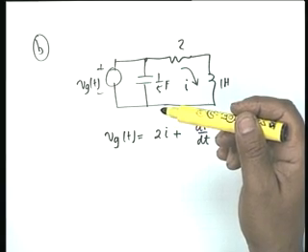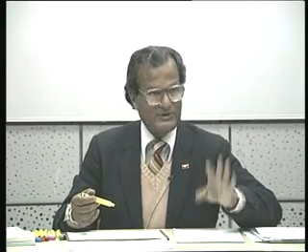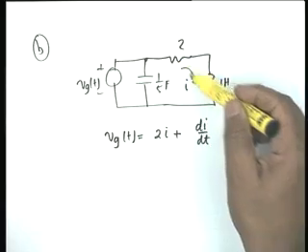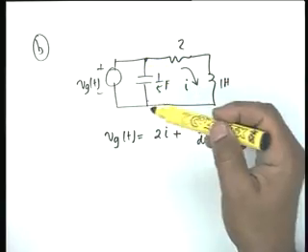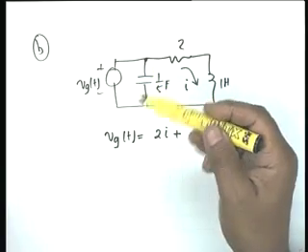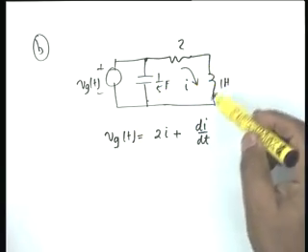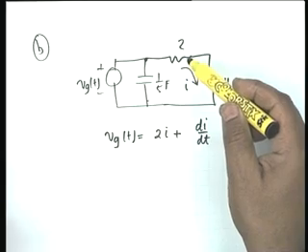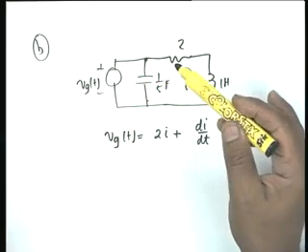By definition, a voltage source is one which maintains its terminal voltage constant irrespective of the current drawn by it. So, irrespective of I, the voltage across 1/5 farad remains constant, and therefore the 1/5 farad capacitor is ineffective in determining the free response of the circuit when the source is a voltage source.